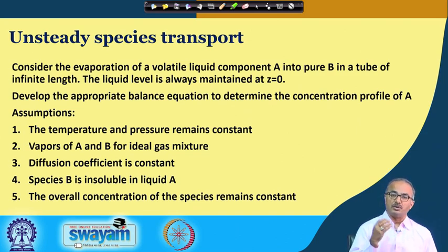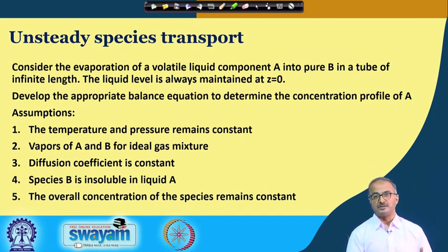Now, the more the humidity in the atmosphere, the longer it takes because this boundary layer thickens. By running the fan, we are trying to destroy the formation of the boundary layer over the wet surface, so that we can maintain a large enough gradient for the solute, in this case water, to go from the wet substance into the atmosphere.